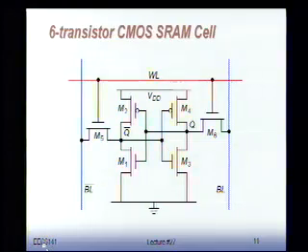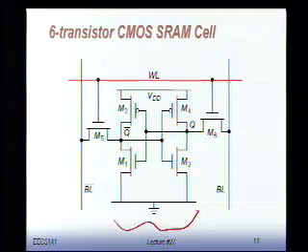This is your typical, very famous 6-transistor SRAM cell. I think virtually any SRAM I know that's on chip today is doing this. A lot of variants on it, but it's always exactly the same type of structure. At the core, we have our cross-coupled inverters. Okay? We have this one inverter, and this is a second inverter, and you cross-couple the inputs and the outputs.